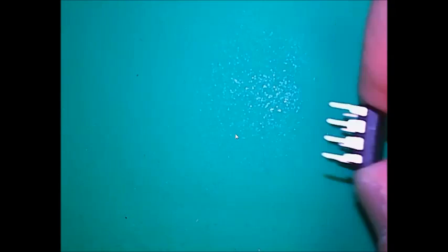But just to indicate what a chip is, this is an integrated circuit chip, because inside this chip are multiple transistors, 15 to 20 transistors. You have capacitors, resistors, a whole network of a whole circuit within this one chip. And so what happens is certain pins are where you connect your battery or your source, and certain pins are where you connect the input, and you have an output, ground, and you have several connections of this within this chip. So let's take a look at what a circuit is first of all.